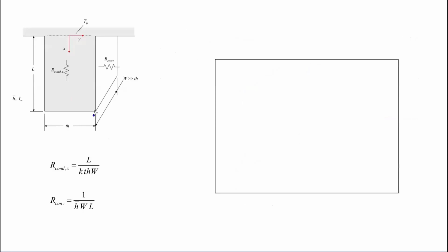Okay. All right, so then that's thinking about resistances in the y direction. But what about resistance in the x direction? What about resistance from the base conducting along the x direction? What's going to happen? Or maybe we can step back and think about what would be the temperature profile in both of the extremes, where conduction in the x direction, the resistance there, is really high versus when it's really low. Okay, so again, let's just conceptually think about this before we get into actually deriving solutions.